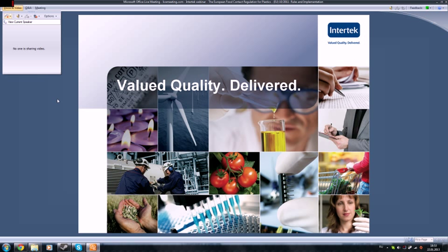There is a 100% migration calculation, which is the easiest one, and you don't need to know which plastic it is. You just calculate down, because usually the substance is given in milligram per kilogram polymer. So if you have 1,000 milligram in 1 kilogram polymer, this is 1,000 ppm in the polymer. But if you look at the EuroCube, you have a very thin packaging on 6 square decimeters. The weight of this packaging might be 10, 15 milligram, let's say 10. So of course, if you have 1,000 milligram in 1 kilogram, you have only 10 milligram in 10 gram of polymer. So only 10 milligram can migrate. This is the 100% migration calculation. So it would be then 10 milligram per kg of food.